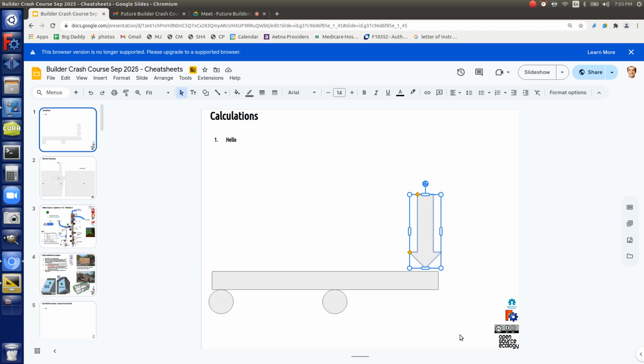ratio, deflection? So you go up to Google now and you say, what is the deflection of a 2-inch rod from a support point 4 feet? So you've got a cantilever of 4 feet. You're pressing down on the end of the rod like that. That's 4 feet. What is the bending moment? Not the bending moment. It will be the deflection. These are deflection calculations, which are very common in all kinds of studies.